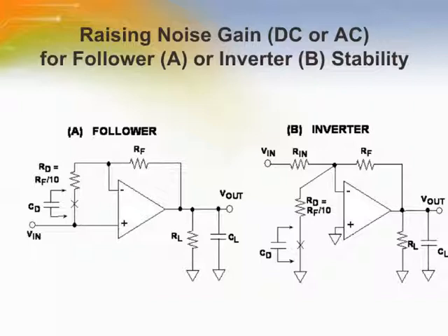It should be noted that some amplifiers such as the AD817 and AD847 series are designed to be stable under any capacitive load. The penalty of this adaptive compensation is increased ring gain on low-level outputs and increased distortion because of the resultant increase in nonlinearity.